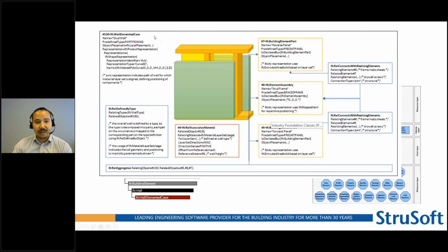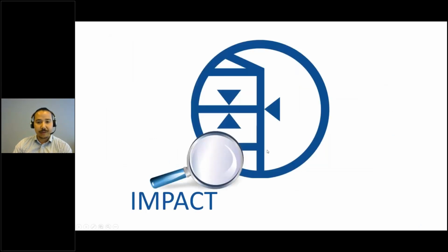So knowing this, or knowing where to find it, can be useful, especially in Revit, where you have the possibility to map a lot of IFC entities to the Revit categories. So you're sure that you get all the correct information from your Revit model over to your IFC model. Otherwise, some things might be missing. But all this technical stuff you can go and read by yourself on the homepage.